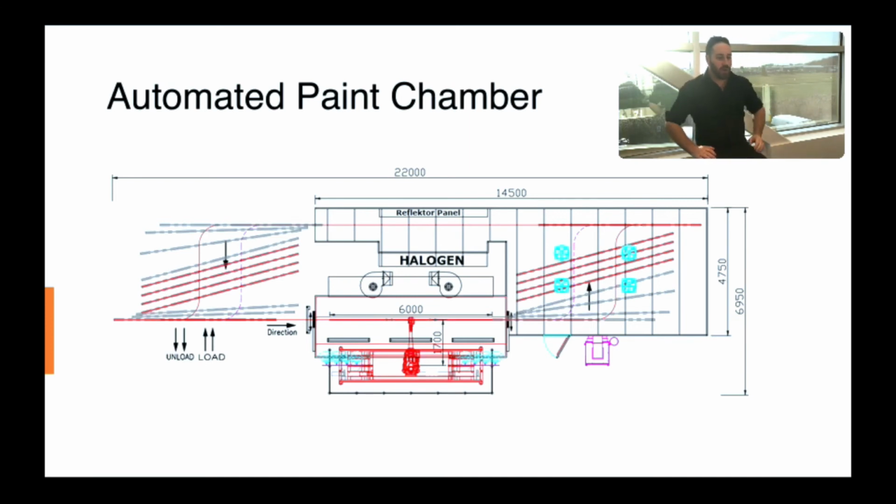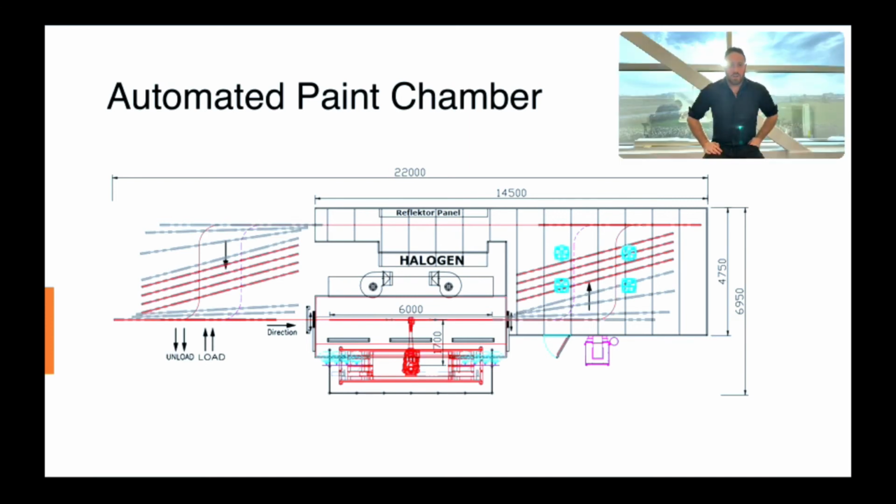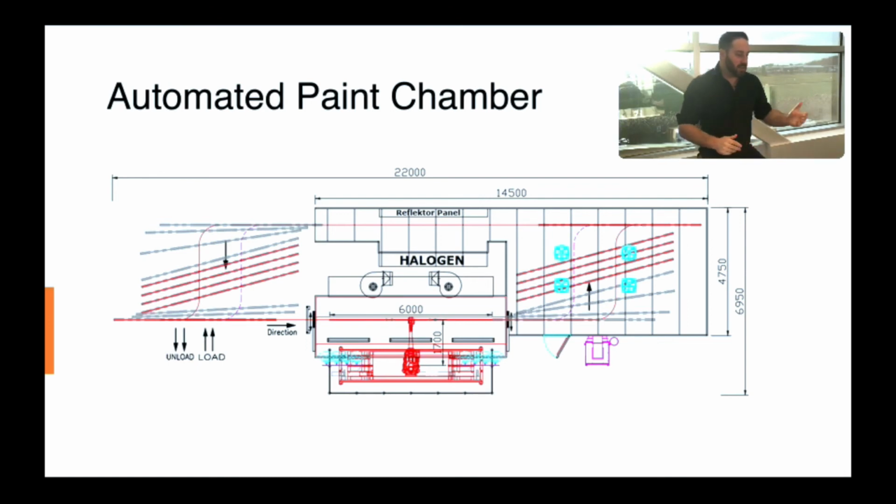The reason why I put this one is that I know that the Western fabricator, if I'm thinking about Toronto to Vancouver, is painting more bars than boxes, while Quebec is painting more boxes instead. But keep in mind that this technology can be adapted to either boxes or bars. You do have to do a preparation on the bars or the boxes, taking off the areas you don't want painted. But this is going to be a system that paints with a robot. So a lot of time is gained there.